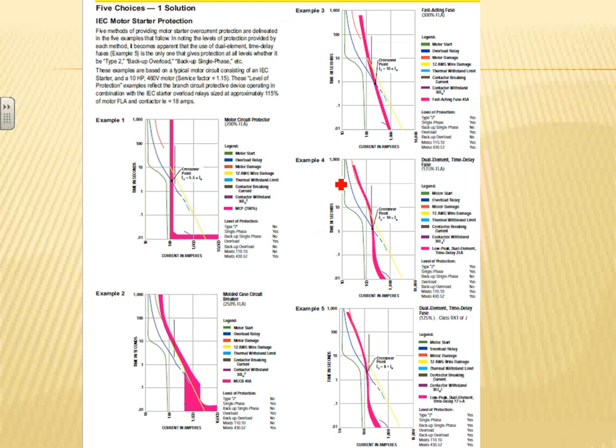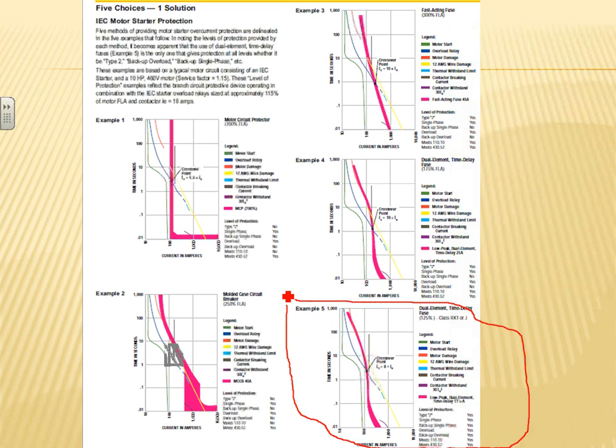I don't know if you guys have seen these curves. I thought this is really unique, especially the last curve here. Again, I want to warn you, this is done by a manufacturer of fuses, so it makes the fuse look nice. So the bottom one here is supposed to give you a lot of protection. You can see all yes for all this type of protection. Would it protect my conductor? Yes. Would it protect my motor? Yes. Would it protect my contactor or VFD? Yes. So this is where current limiting fuses become a big deal. If you have current limiting fuses on the equipment, supposedly it will provide complete full protection and overload backup for that particular machine.